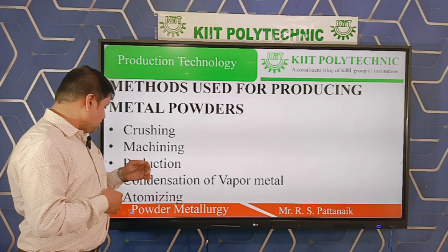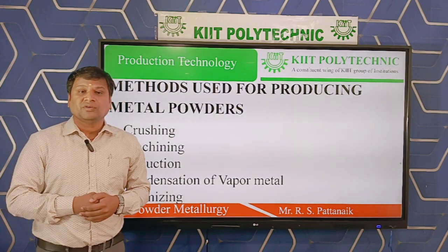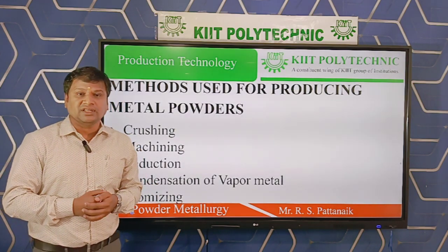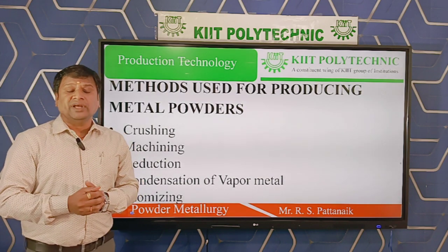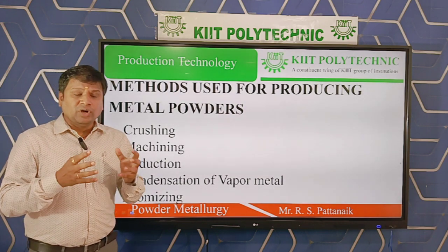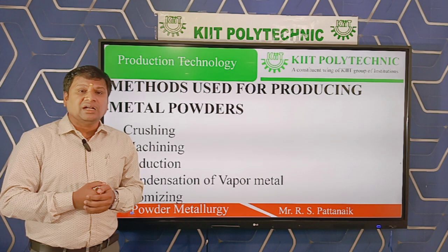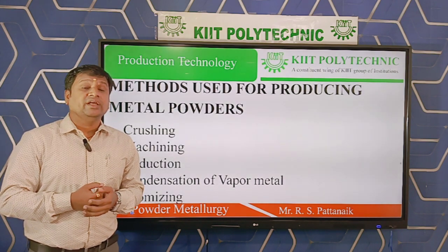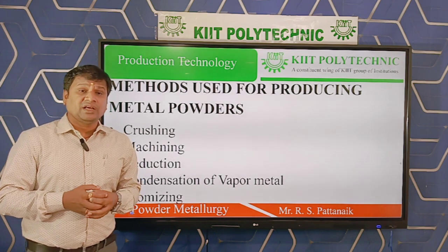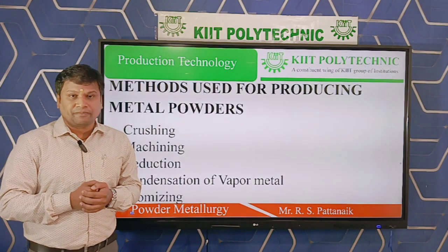The next method is atomizing, a very important method. In this method molten metals are forced through a nozzle into a compressed air or water.